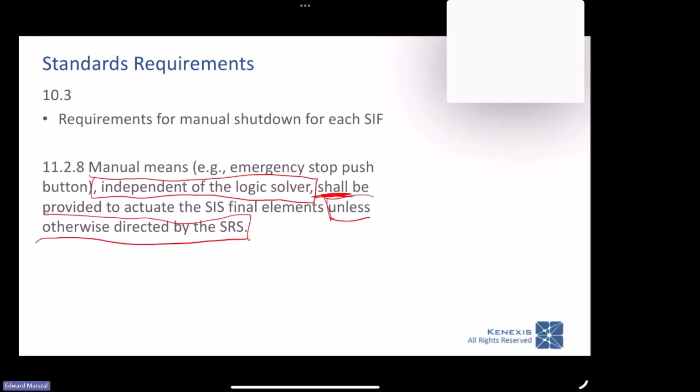So the water dripped everywhere, not just the safety PLC, but the control PLC. Now the plant's going out of control. Everything's going haywire on the plant. Alarms are going off everywhere, but the shutdown system isn't closing the shutdown valves because the safety PLC short-circuited and it's shunting power out in the field, forcing all these valves to be open when they need to be closed. So what? They've got no switches. They have no manual shutdown switch that is going to de-energize the power to the field.